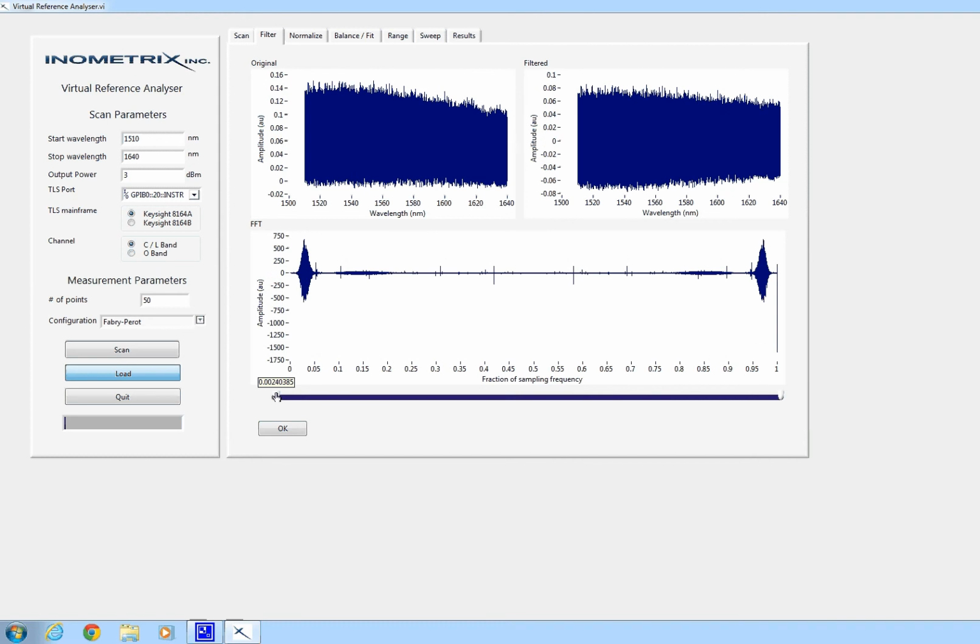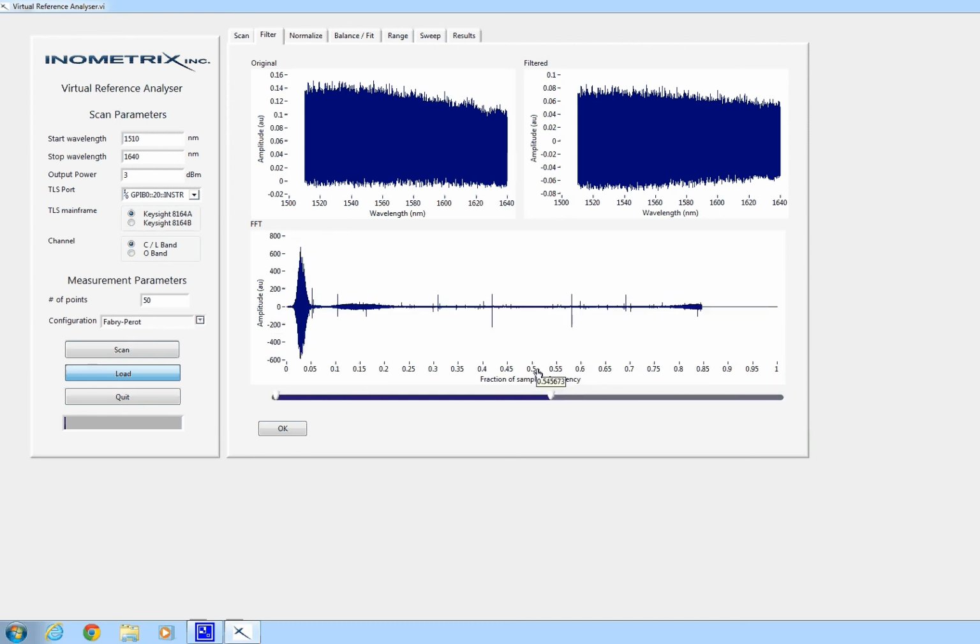So what I'm going to do is remove the DC component to show you that there are two peaks here. This is where all the information is. It's in the peaks. Since it's mirrored, the information is doubled. We can actually just remove this half because it doesn't change anything, since the information is on this side of the FFT of the interference pattern, and I can remove the high frequency without any issue here because all of the dispersion information is in this peak here.